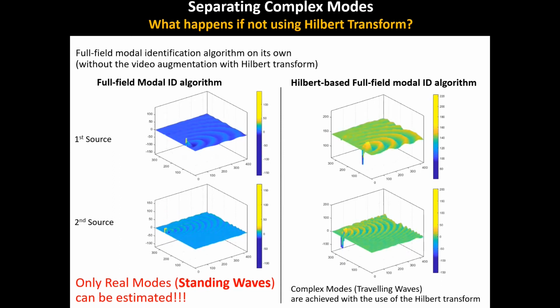From these, it's clear that the modes reconstructed by the earlier technique are simply decompositions of standing waves, proving its capability to only extract real modes. On the other hand, when using the Hilbert-based technique, the individual traveling waves can be clearly visualized, indicating its suitability.